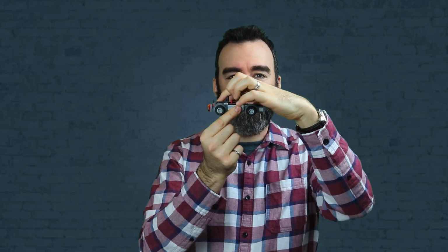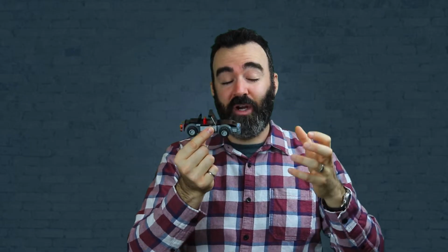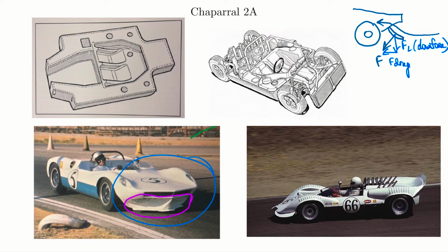Okay, so in pushing down here, they realized, well, now they need an equalization force at the back. Okay, so they need some downforce at the back, right? So they still have traction on those rear tires as well. Those are the tires that are driving the vehicle. So with all that they'd learned, they actually made a new version of the 2A between '63 and '65.